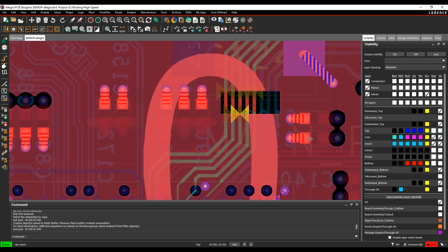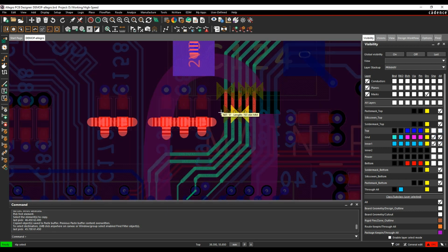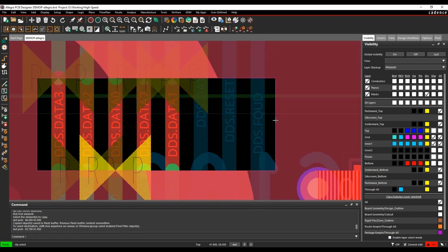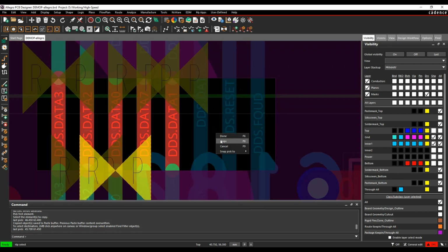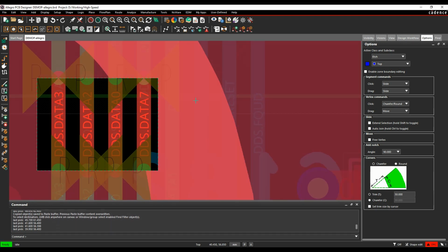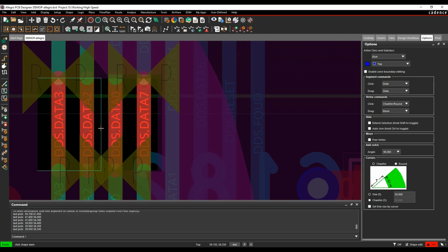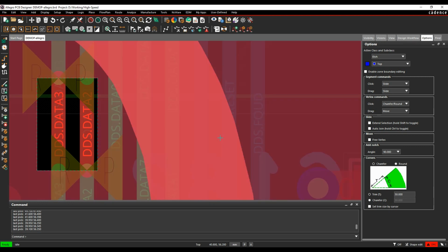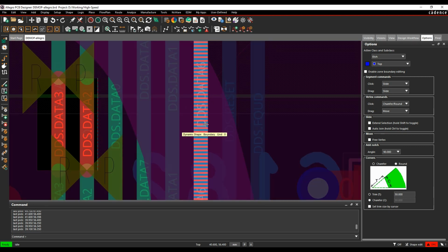If we turn my ground plane on, you can physically see I've got a void left in from a previous design revision, so I obviously need to adjust this. Now this is a live link. So if we go into shape edit mode and slide the segment, you can see this one then updates from a color point of view. These four are still involved. It will physically update as I go along using the Vision Manager and the Vision options. So that's Return Path Vision that's available in the high-speed license.